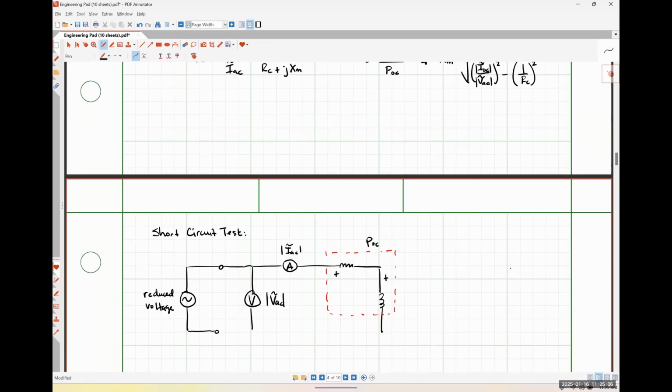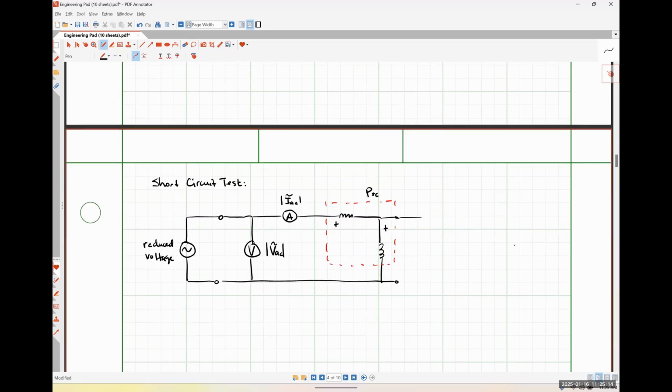And then we actually have our connection to our transformer finally over here. And I'm just going to depict this as just the schematic symbol of a transformer for right now, where this is our high voltage windings yet again. This is our low voltage winding. And then we short circuit these guys such that rated current is flowing in our low voltage windings.